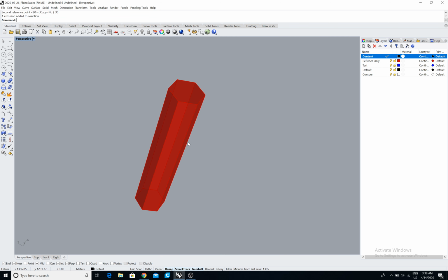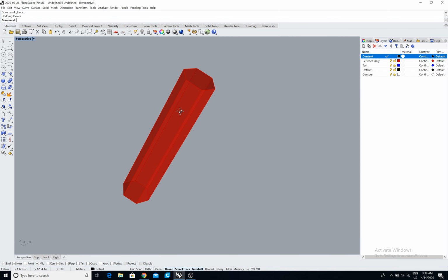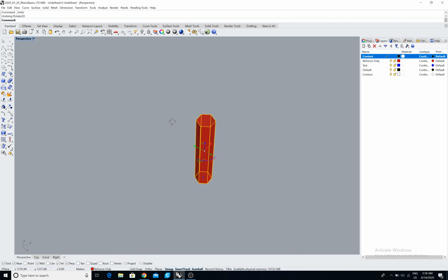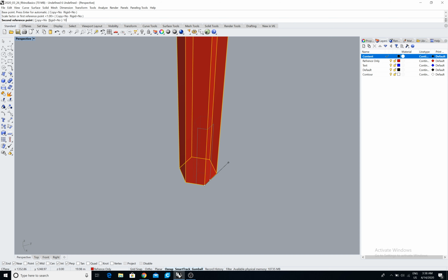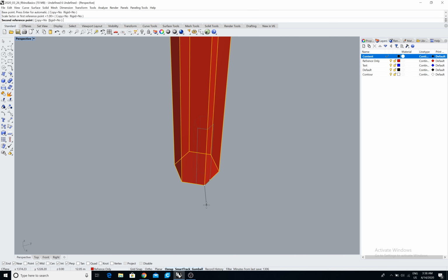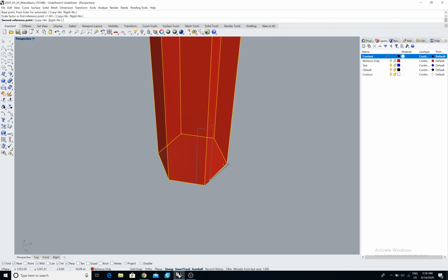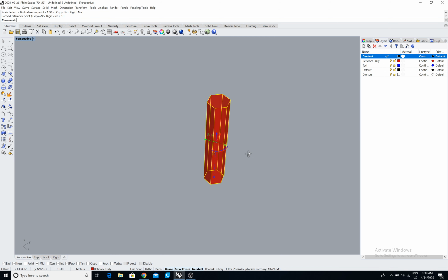So that's about rotate 3D. Okay, then I have scale. So scale, as we are all familiar, if I write scale, I just have to press enter, give two reference points, and either I could scale it with some distance, let's say 10, or I can just specify a factor. So if I say 10, it will get scaled up by a factor of 10.